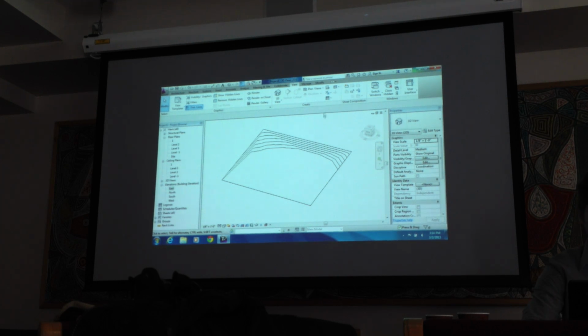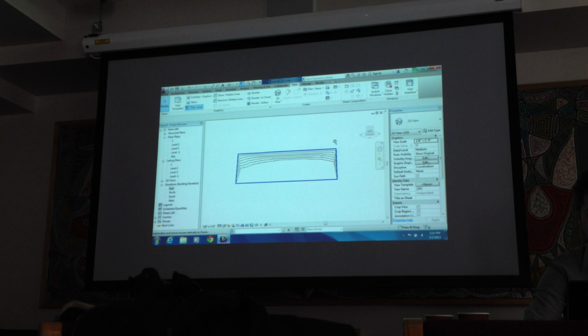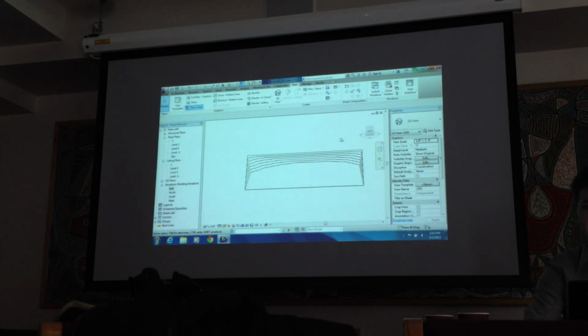If you hold shift and click the scroll, you can rotate around the entire site. Or you can hold control and the scroll tab, and it allows you to zoom in and out. And if you just use the scroll without shift or control, it allows you to pan through the site.